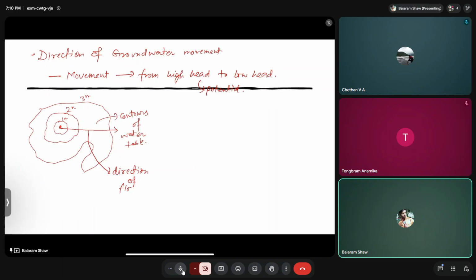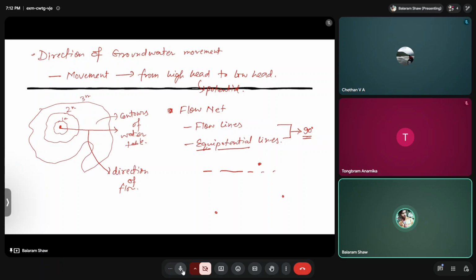Okay, so this equipotential line we generally get through how much head we have at which location. But we also see that in many areas it is not possible to obtain sufficient data to construct this kind of water table or piezometric surface maps. So what we generally do, let's say you consider three wells, you see three wells somewhere. Now we know that here the water table is somewhere 27.5. Here maybe it is somewhere near 27.0. So these three are the observations that you have.